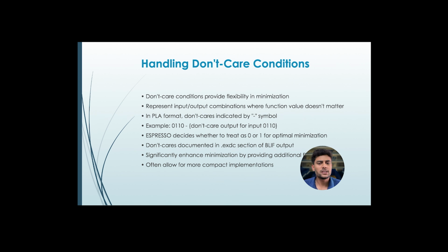Moving further, we have handling don't care conditions. Don't care conditions provide flexibility in minimization. It represents input or output combinations where the function's value doesn't matter. In PLA format, don't care is indicated by a minus symbol, or we can say dash symbol. For example, we can take 0110 dash, a don't care output for the input 0110.